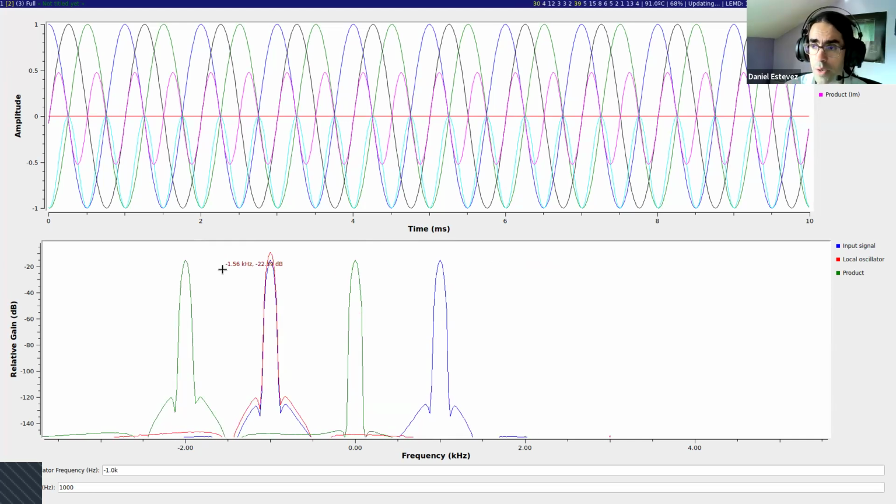So in the case of the FM radio station, if we are tuning to 95 megahertz, we would get the intended signal at 0 hertz or near 0 hertz, if there are some frequency errors, and we will get something at twice 95 megahertz or minus 2 times 95 megahertz, which is 190 megahertz. And there is a filter which removes all the high frequencies before converting to the digital domain. So that is one way of doing things. Basically, you translate things and then you remove this with a filter.